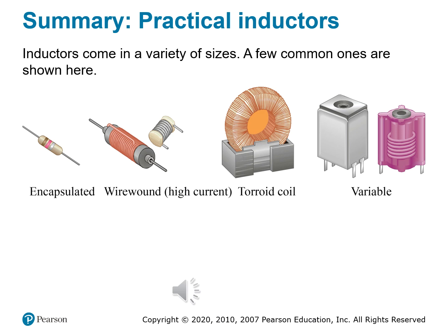You also have shielded inductors, as shown there in the rectangular metal housing. That's often part of an RF or a switch mode circuit where EMI shielding is essential. The metal case prevents field radiation, making it ideal for dense PCB layouts.